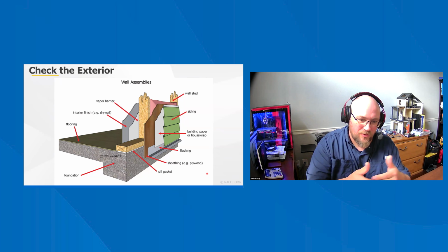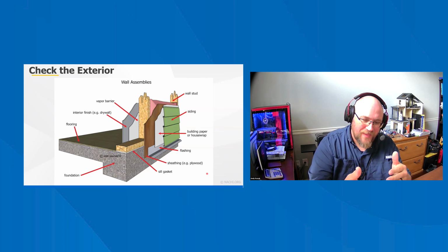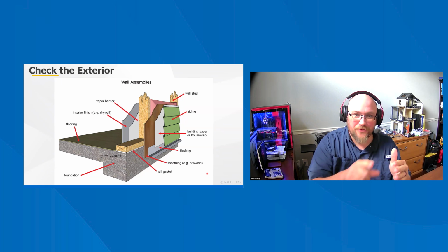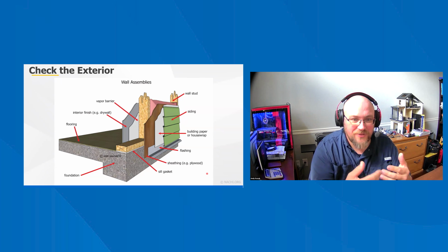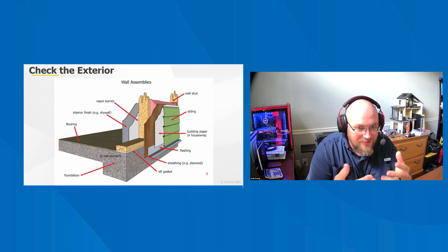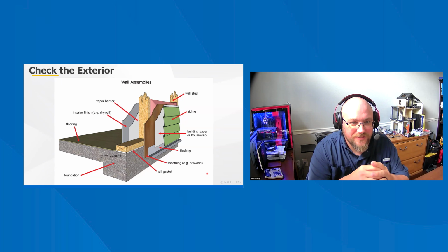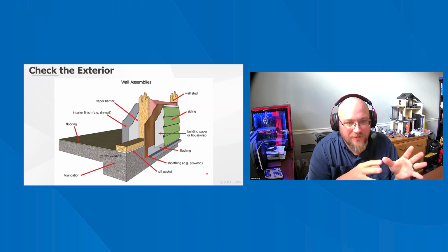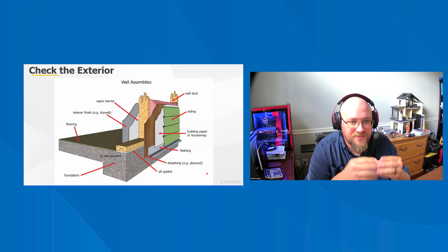They basically cut that hole or used a drill and cut through the house wrap, and then they don't seal around it. And you can tell that because you could see the house wrap fibers that are just hanging out there right next to the water pipe. So that's how I tell on a new construction house or an existing house.